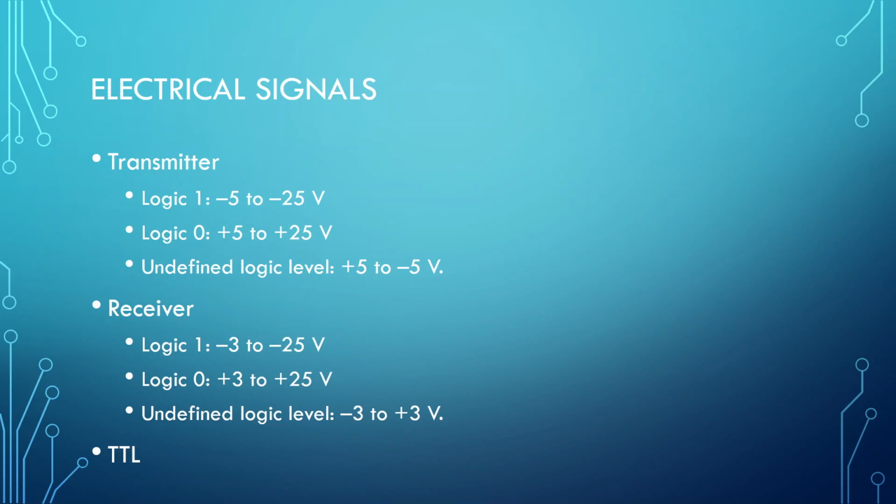That would be your current. But anyway, you can figure out how much power loss we have, because you can say, well, 1,000 feet of this cable has 2 ohms of resistance loss, and if we're going to be running at 5 volts, we can figure out how much current we're going to be using. With that current, we can figure out what our voltage loss is.